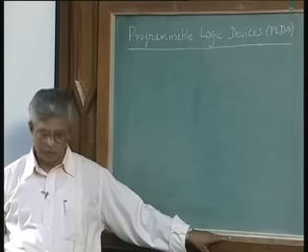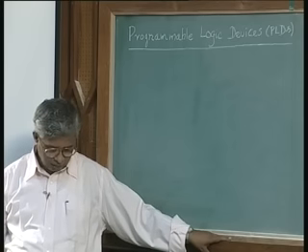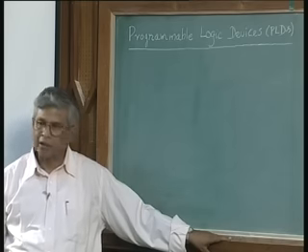What is a programmable logic device? Now we saw in the lecture on multiplexers, combinational logic design using multiplexers. It is easy to make the circuits function based on the hardware available, rather than go to the Karnaugh map minimization technique of reducing the number of gates. So, as the circuit complexity increases, we do not want to go on building gate level logic, we go for higher complex hardware and try to map the given circuit specification to this hardware available.